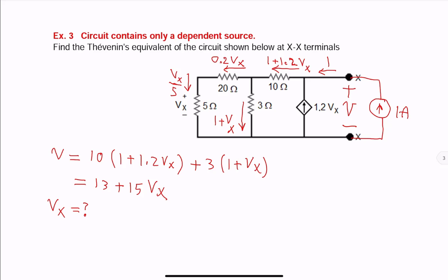Let us apply Kirchhoff's voltage law to the mesh on the left-hand side of the circuit. Let's go clockwise. Starting at the lower left corner, voltage is negative. We see negative of Vx first, so negative Vx. Through 20 ohms resistor, we are moving against the direction of the current. Again, we are using voltage drop, passive sign convention.